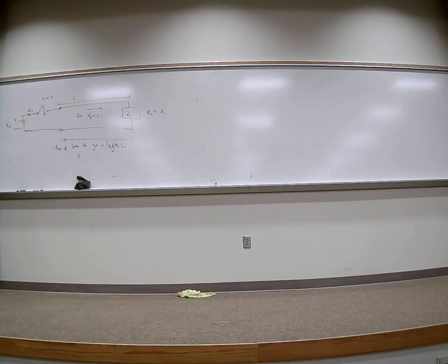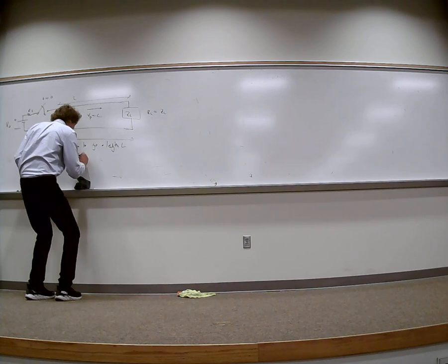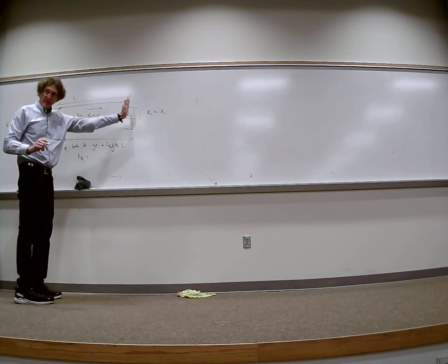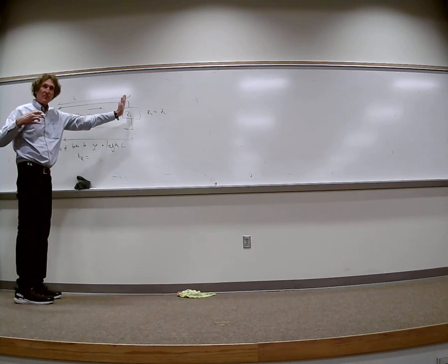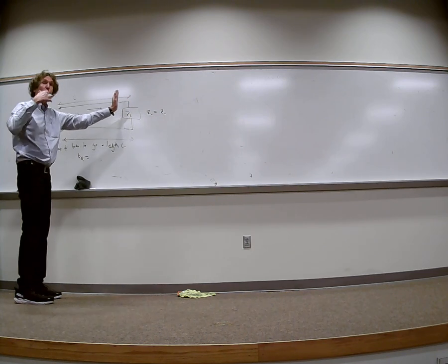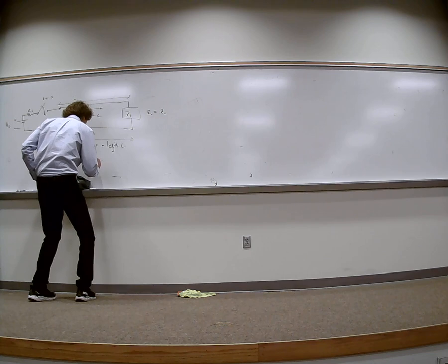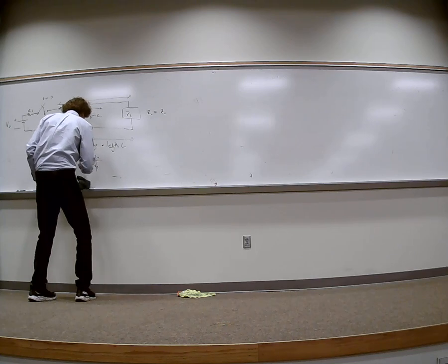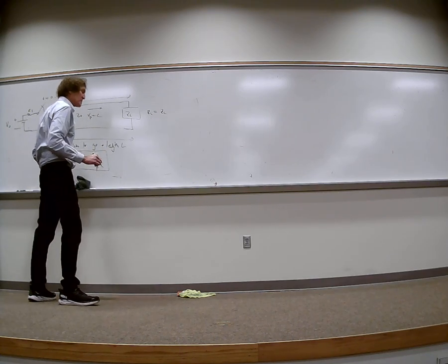I teach this from several different books. Yeah, TL. So TL is just the time it takes for the wave to start propagating and finally hit the load, go down one length. Y'all follow? It's just the time it takes to go down one length. So that's just going to be the length of the line divided by the velocity, and I'll call it the phase velocity here, even though we're going to assume c. That's the first thing that's important.